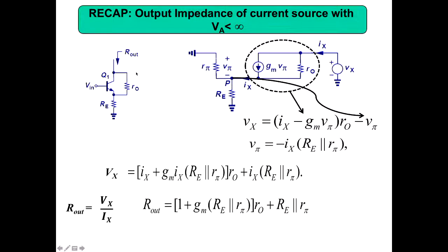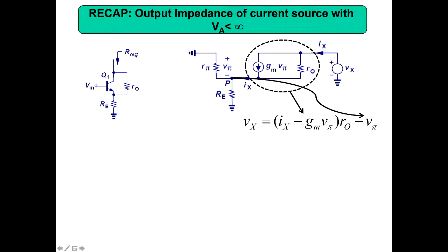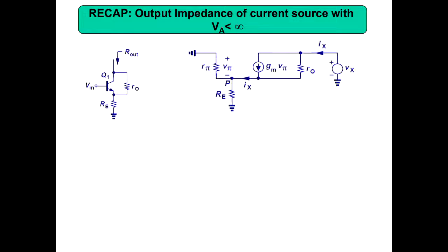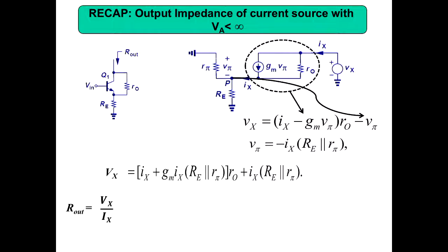So in the current source, what we are doing is reducing this slope further down and pushing it to the ideal one. That is very good when we design the chip, especially amplifiers. So when you design a current source now, you will not simply use a transistor, rather you will use one Re as well, so that your output impedance is very high.